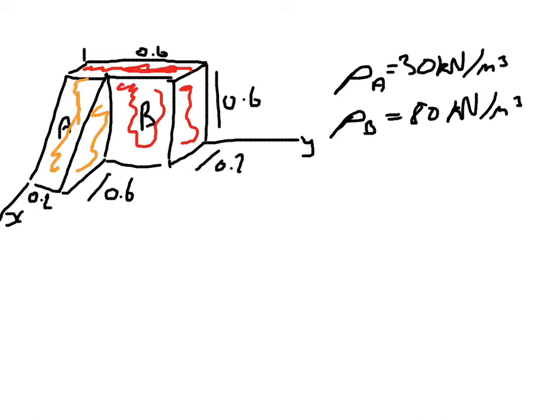Okay. The first thing you're going to want to do, probably, is work out the weights. So you should have had a go at this already. I'm going to draw the table if you had no idea where to start. You're looking for a centre of gravity, so you're going to need to use weight instead of just geometries, but the principles are no different. You're using a weight instead of an area.